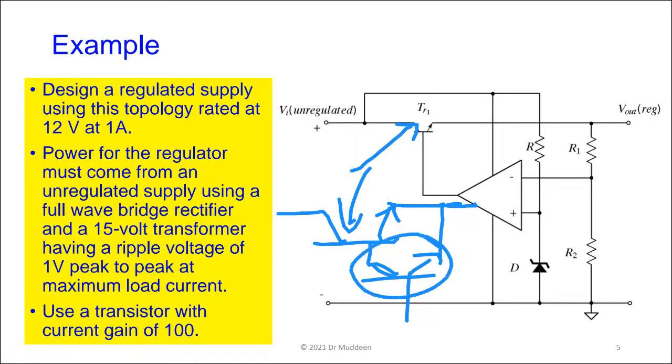This is a smaller transistor in there, and the net gain of this thing, remember, is HFE1 multiplied by HFE2. So a much higher current gain, meaning that the current required here is a lot less than in the single transistor version. Okay, and Darlington transistors can also take a very large amount of power.